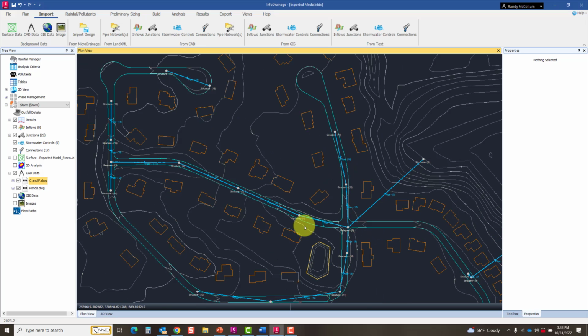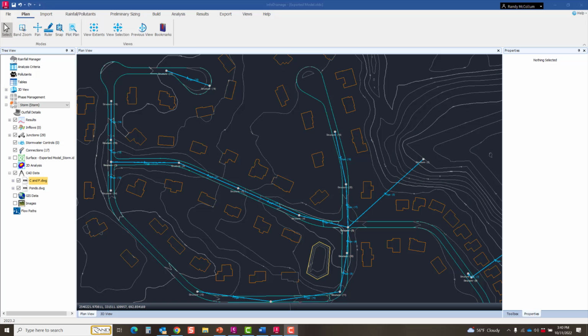Now, in this exercise, you can set up inlets, and you can go through the process of sizing the inlets and doing bypass flows and all of those things that you might be used to in storm and sanitary analysis. However, just to simplify the analysis, I'm really going to focus only on this main trunk here with the branch along it. And because we're doing a storm analysis, like every other program, the next step I need to go through is creating sub-catchment areas for each one of the individual manholes and assigning some sort of rainfall data to them, or IDF curve. Another nice thing about this program is it gives me several ways that I can accomplish that.